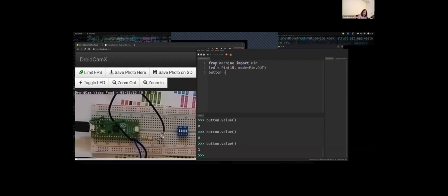Okay, so it's all labels. Labels can be anything that you choose. There's nothing wrong in choosing whatever label you find convenient. And you can use Pin of 14, mode is equal to Pin.IN. So the first one is an output pin, the second one is used as an input pin. And then I try to print, if at all I try to say LED.on, LED.value of 1.